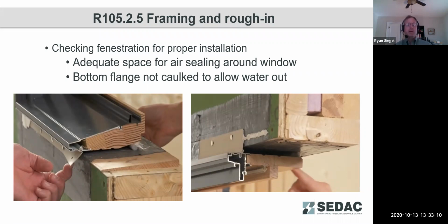This is where, between the water seal and the air seal, there's a chamber. In the event that any water does get past that water seal, it can enter this chamber, work its way around to the bottom of the window, and then make its way out of the assembly.